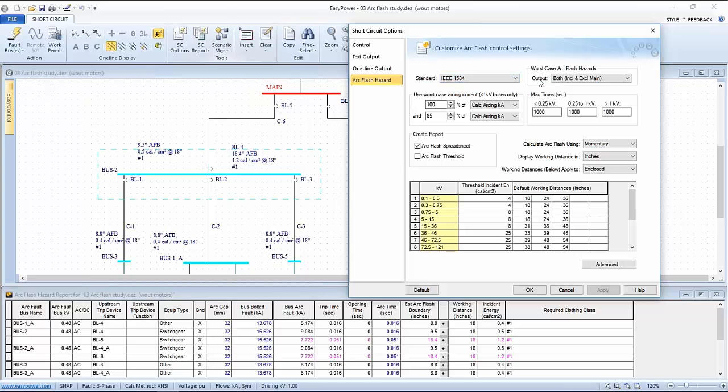And again, it has nothing to do with the confidence that this breaker will work or not work. It has everything to do with a physical barrier that would prevent an arc from jumping from the input connectors to the downside or the bus side of this main breaker.